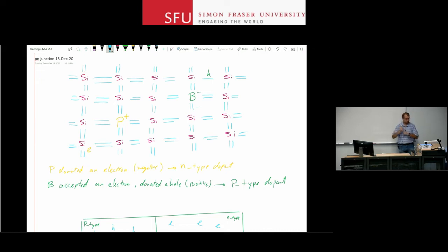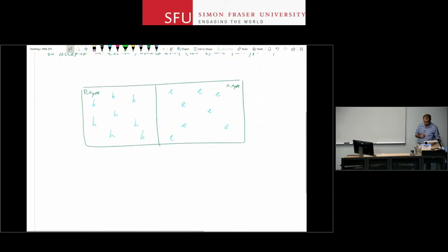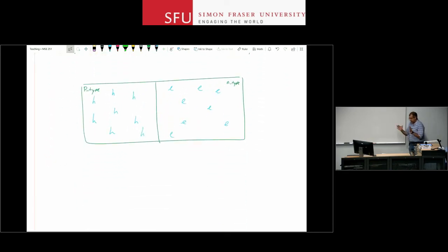It's a positively charged ion, right? So for every electron in the network, I have a positively charged ion. For every N-type dopant, for every hole, I have a negatively charged P-type dopant. When you bring these two materials very close to each other, what happens is diffusion.